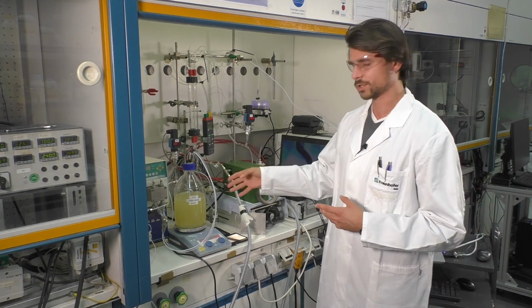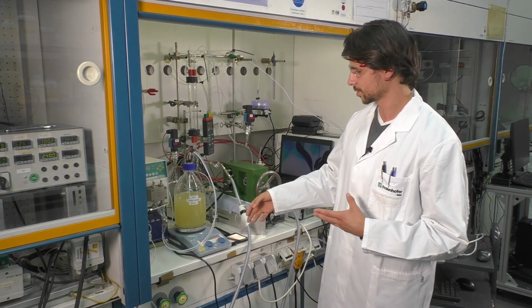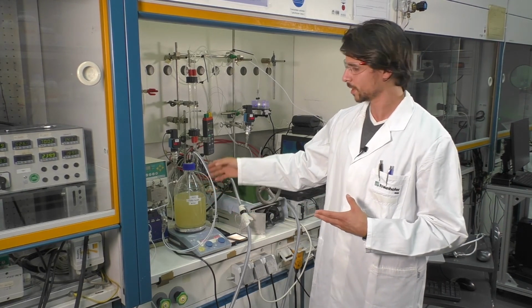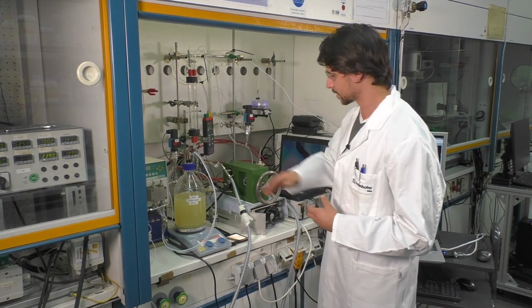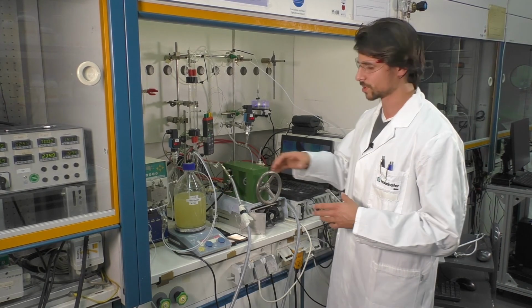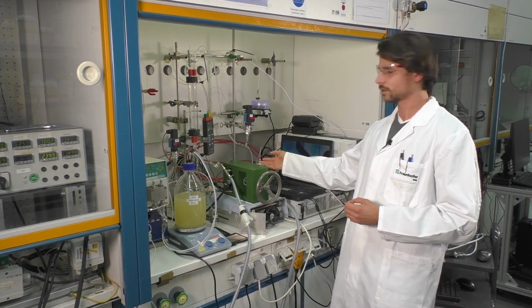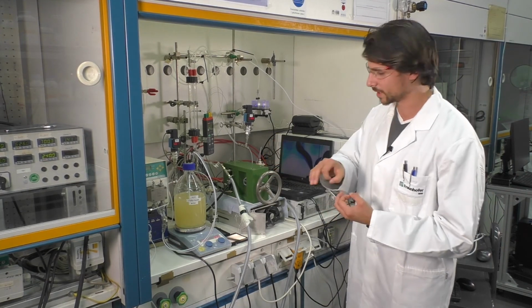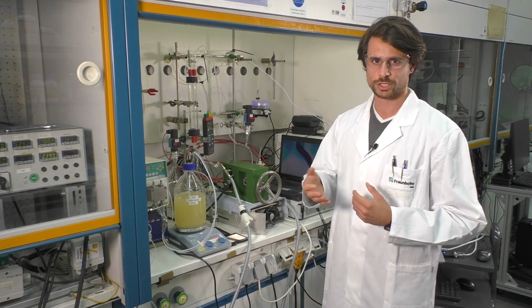So to do the reaction, we pump this reaction mixture, which is some kind of solution or emulsion and is stirred all the time, with an HPLC preparative pump to the electrochemical microreactor. As you can see, we have a distributor here and we use a small diameter to come into the reactor, and at the other end, we also have a small diameter to realize some pressure drop.